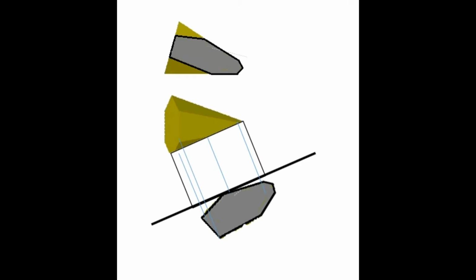And now for drawing the auxiliary view, you observe that I have taken one plane which is parallel to the section plane, as you can see above, and I will project lines from each and every edge which has been cut by the section plane to get the true shape, which is actually similar to the sectional front view. The section portion of the front view and this are the same, but this is drawn with true length, which we will see while drawing.